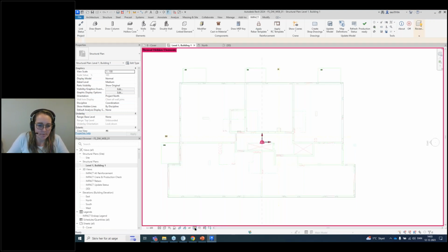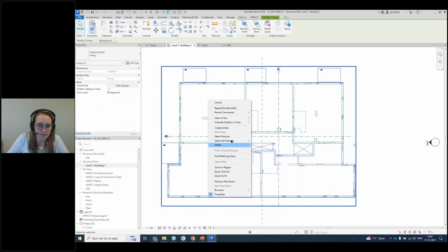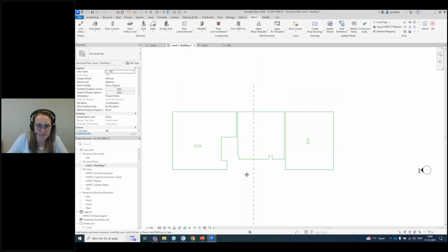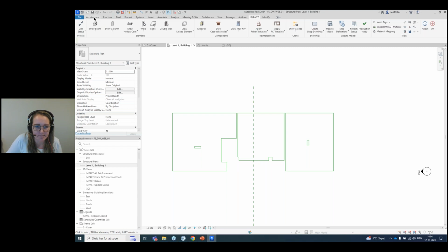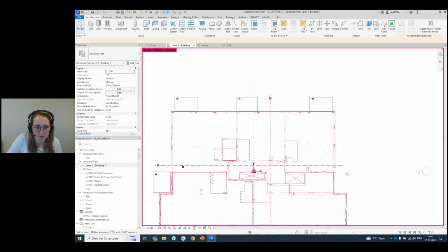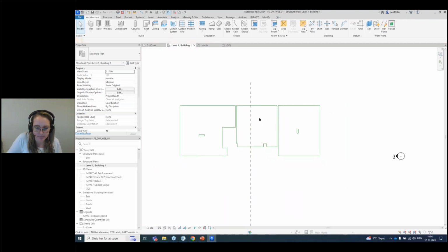I'm going to switch off the underlay now, because when you draw a form slab, any kind of slab, then you probably want to have some areas, and I really like to have control over my area, over my boundary. So what I do is that I do some model line. You can do it with just pure Revit, draw some model lines that you can see as just answering to the boundary. And here we want to draw a Formslab.